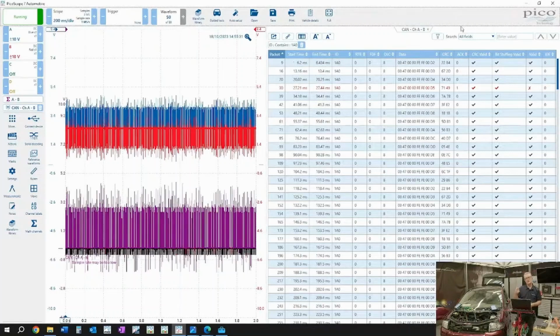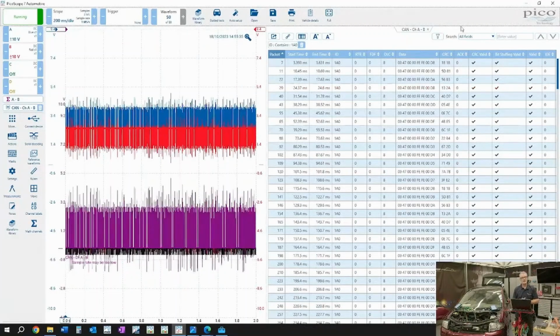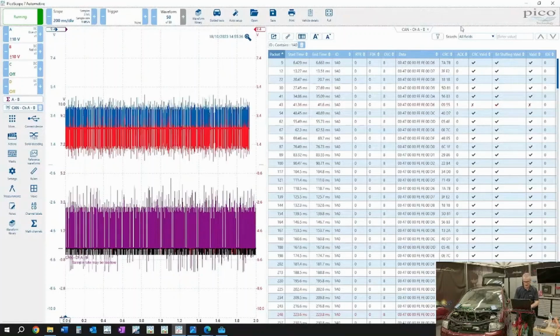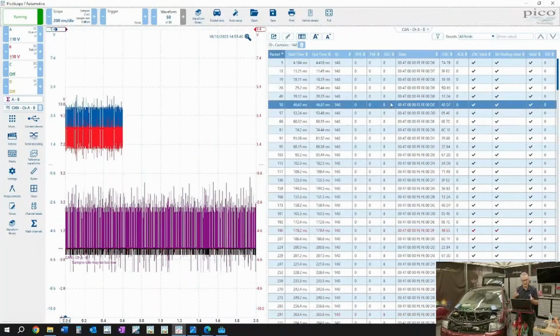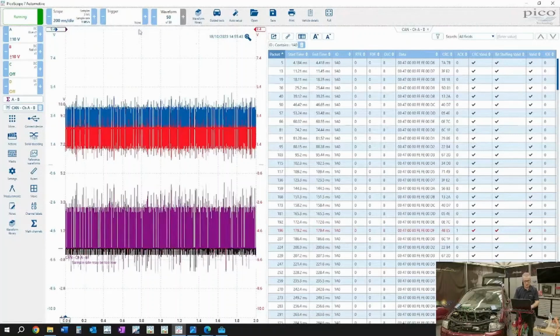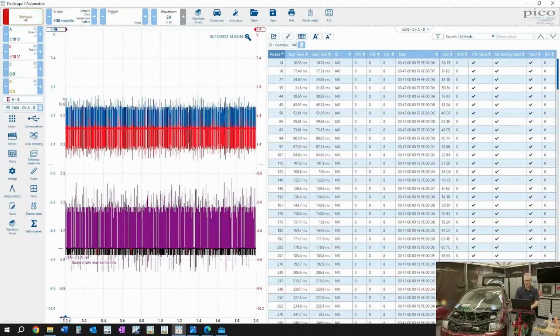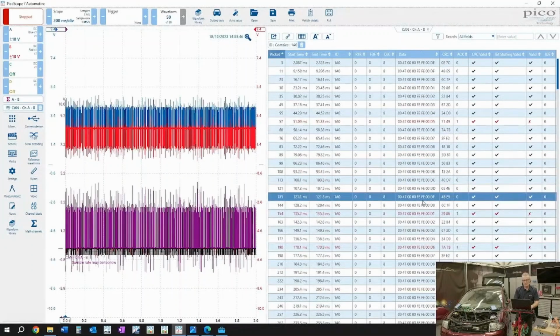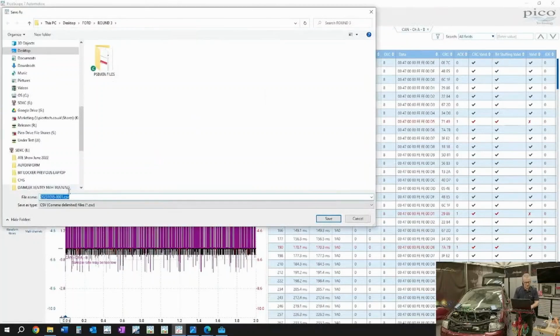All right. It may be that you want to discover or learn what other IDs are associated with this 1A0 ABS ECU. So let's first of all stop PicoScope. You have an option here to export data. So we can export this data to CSV. Everything that you see in the decode table now, we can move across to CSV, and I'll just call this Audi export. I should have called that Ford export, shouldn't I? Should have, yeah. Sorry. And click save.